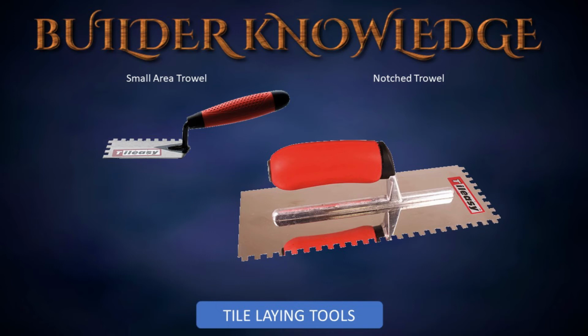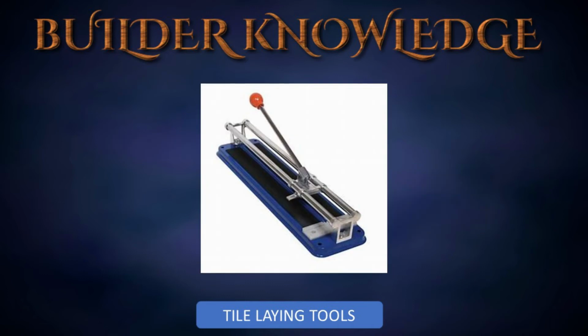There are many tools you can use in laying tile. Let's get started with the notched trowel, the primary tool for working mortars and adhesives. A trowel that is notched on one side and smooth on the other is preferred. Many different sized trowels are available. If you are using a notched trowel for adhesives, refer to manufacturer's specifications determining the notch size. The tile cutter is the most efficient tool for cutting ceramic tile.